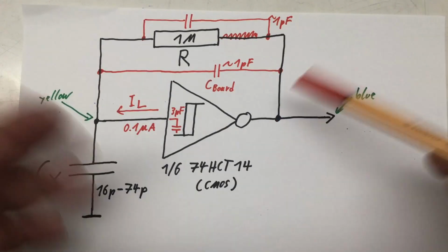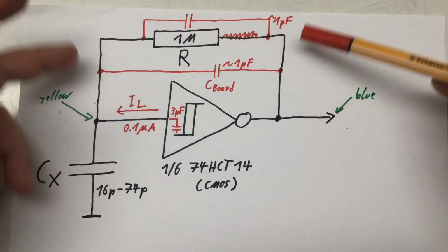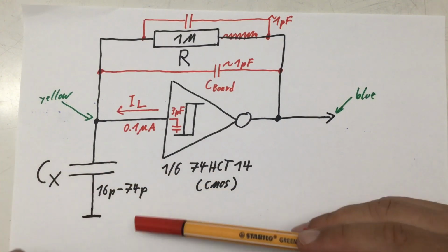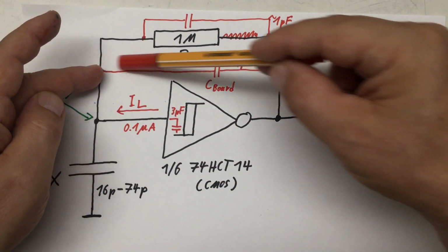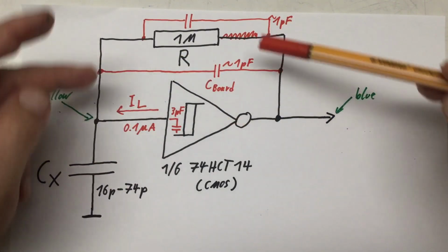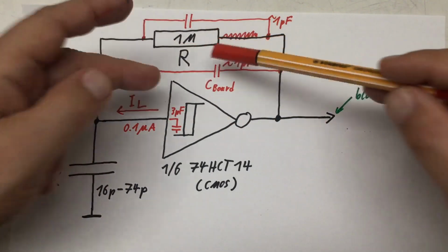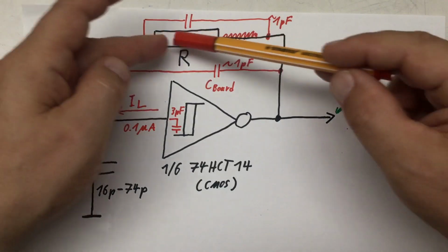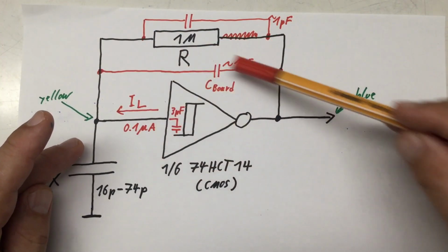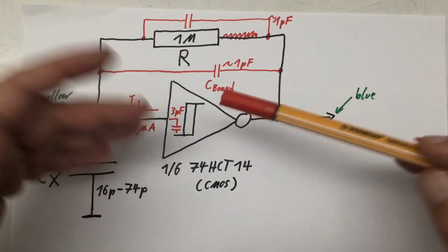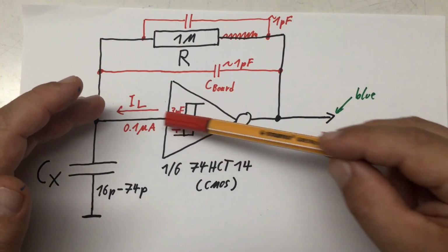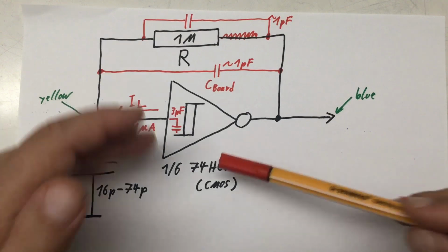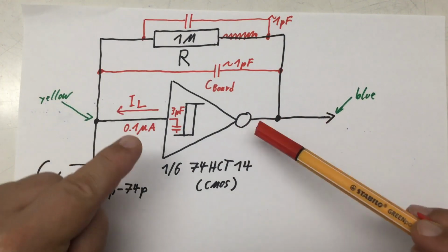When designing the PCB, you should probably avoid parallel traces between the output and the trace connecting to your capacitive sensor, trying to minimize that parasitic capacity. Also, you should choose metal film resistors because they have a lot lower parasitic capacitance than carbon film resistors. Also, for the inverter you choose, you have to consider the leakage current and the capacitance of the input. I mean, the 74HCT14 is not bad, but you can do better.